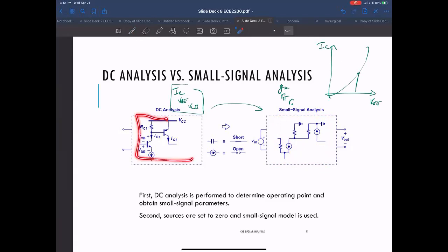Again, remember we talked about op amps in a typical scenario might have 15, 20 transistors. Anytime you want to design or analyze something, you don't want to be solving 20 exponential equations at a time. So you want to be doing things in a much simpler way. And that's where the small signal analysis comes in. We figure out where our bias elements are. That tells us our small signal parameters, which are all functions of these bias parameters, and we create the small signal models.